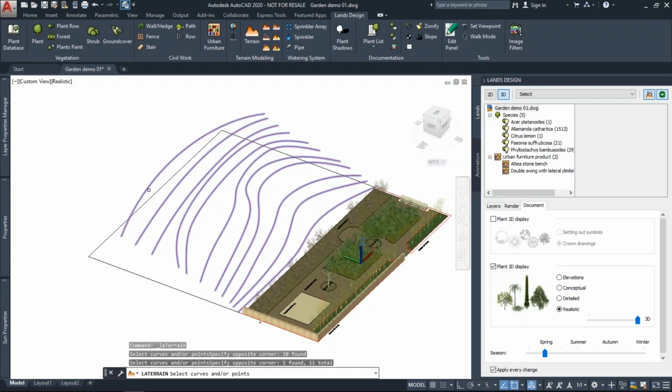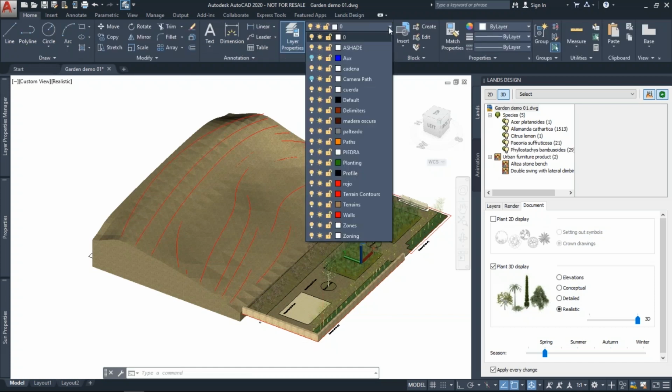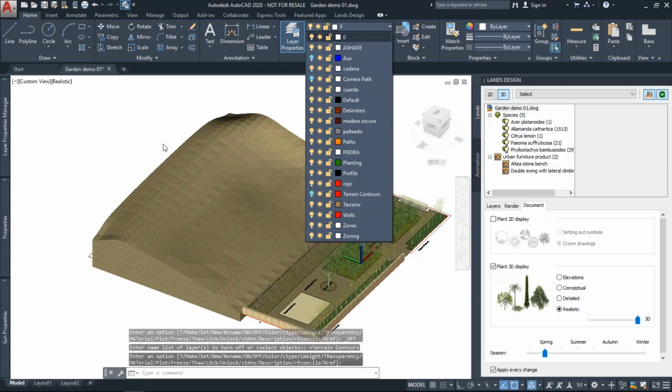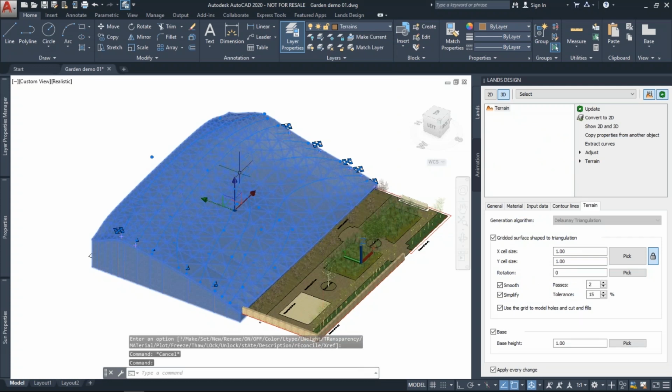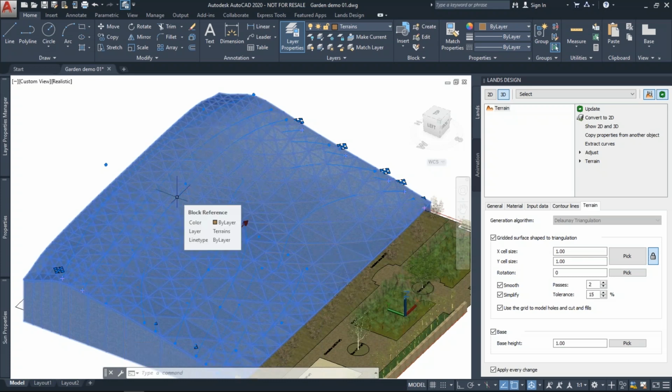I have these curves in one specific layer, so I'm gonna hide them for now. It's called terrain contours, because now I want to highlight that we can still modify the topography of this terrain just by changing the position of these control curves. Okay, and well, modifying them as if we were modifying the original contour curves. So we can change the topography of this terrain by these control points.